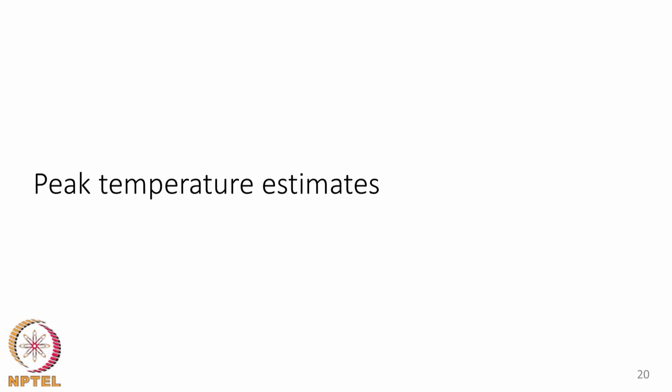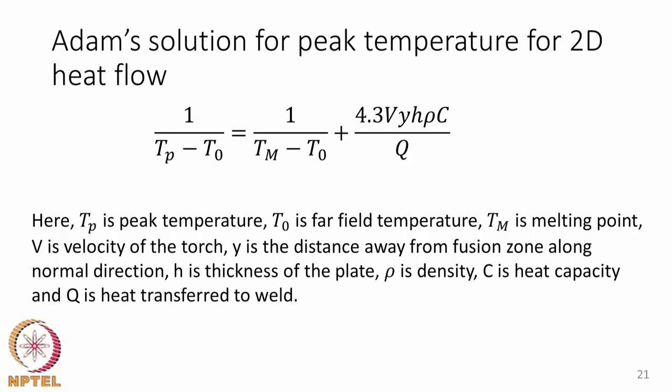Apart from the Rosenthal solutions, we also have some analytical expressions available, attributed to Adams' work, to show you what would be the peak temperature achieved on the top surface upon heating, and this is usually used to estimate the peak temperature under laser heating. These expressions are much simpler and can be used as a calibrative exercise to find out how to go about the numerical solution later on.